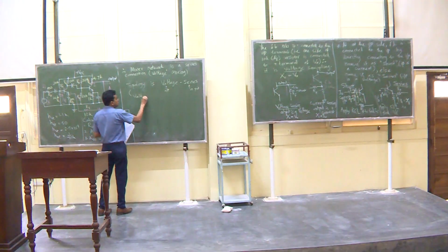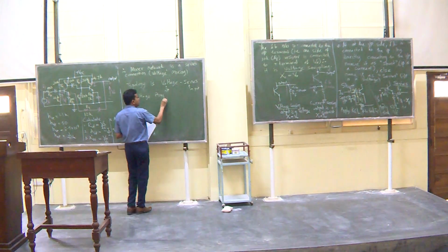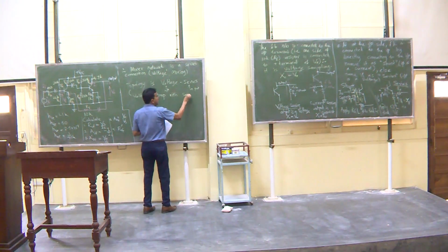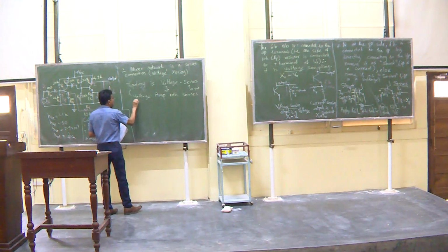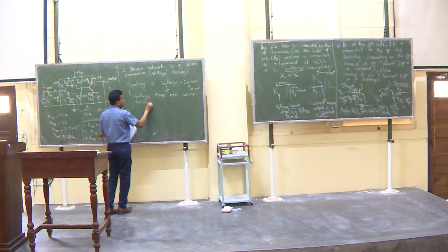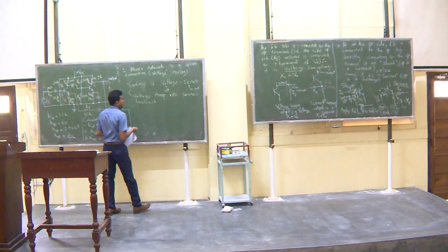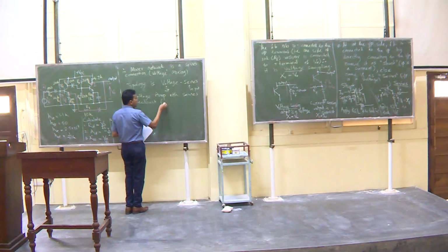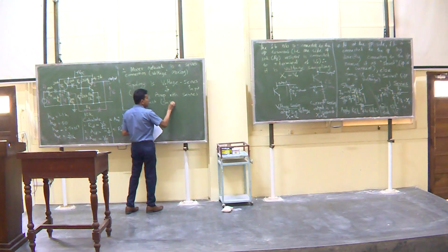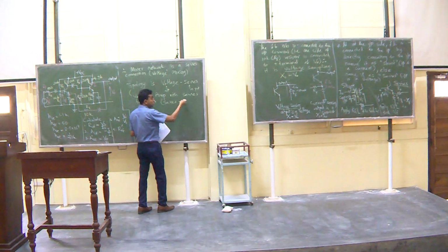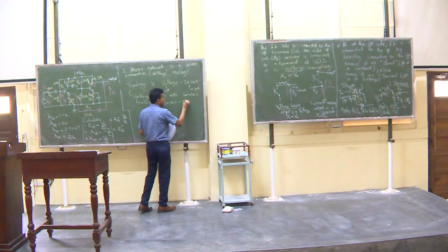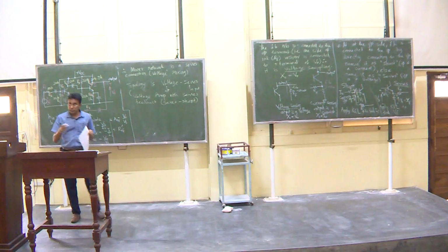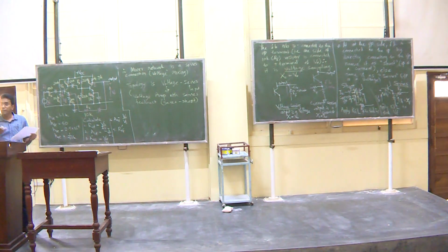Voltage amplifier with series feedback. That is why we call it like this. So, therefore, input is a voltage, output voltage. This is the same as input is series, and you measure the output in shunt. So, this is series shunt topology. Series shunt topology is the same as voltage series, right.